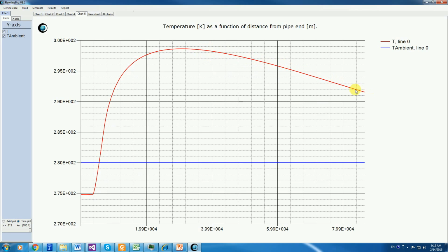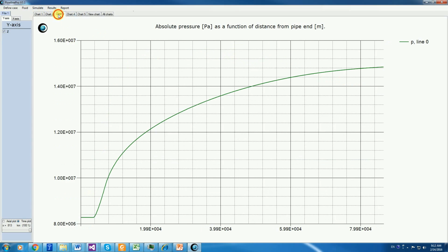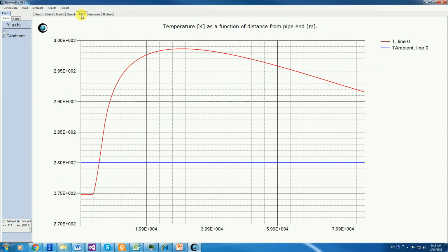We remember, here at the last part when we looked at the pressure, we can go back and look at the pressure. This is the pressure at the outlet. We see the pressure goes up all the time, but it doesn't increase very fast here. So then it turns out we are losing heat faster than it's produced by the compression. So we reach a maximum temperature. Not the problematic temperature, so there's nothing really to worry about here.